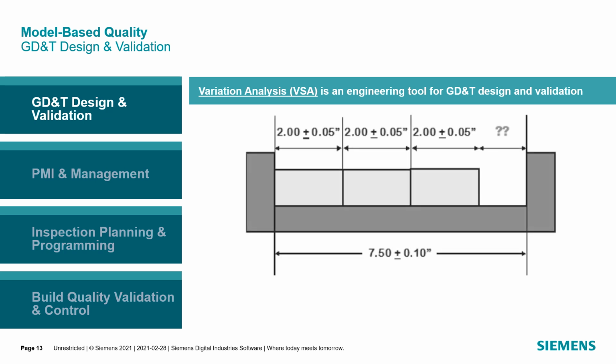Tolerance analysis or stack-up study is an engineering method for understanding how the variation of individual part geometry features and the variation of their assembly process contribute to higher-level key product characteristics, also known as KPC. Those top contributing variations are identified as critical to quality factors, also known as CTQ, and are to be closely monitored and controlled during manufacturing. Therefore, the CTQs are also often referred to as key control characteristics, or KCC.